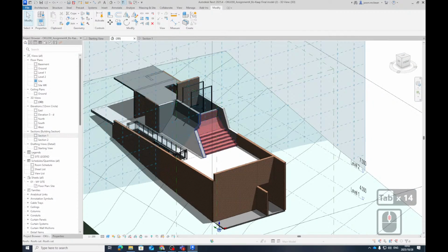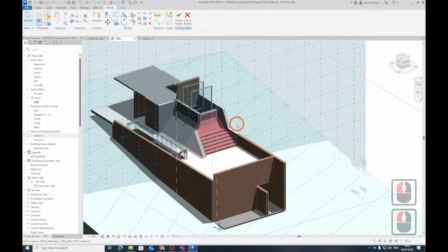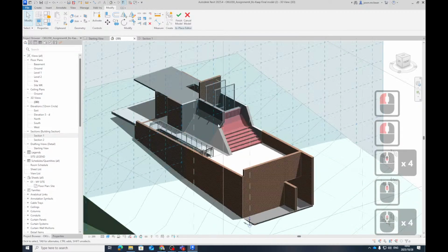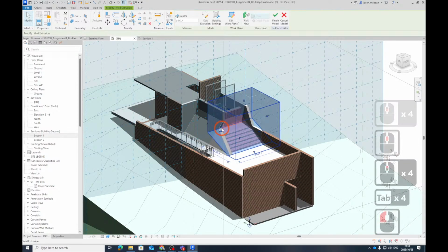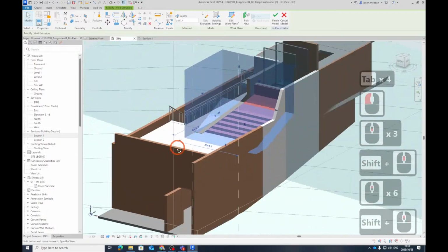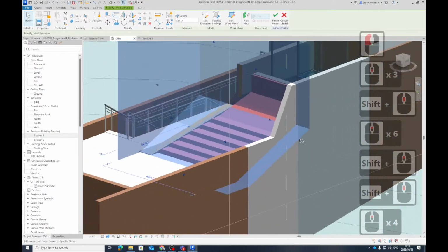And if you give this in-place family a name, you see this roof cuts. So now if I select and I go and edit in place, I can see the object. You can't see it now, so you just have to hover and tab sometimes. That's telling you void. Then you can go and edit this thing as you need to. Okay. Thank you so much.